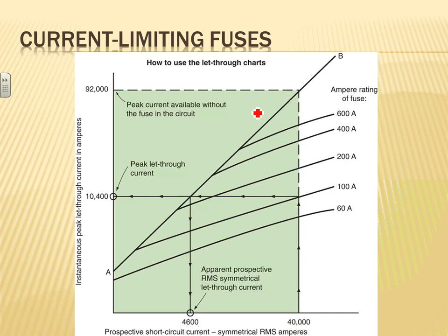So the more elevators you have, the easier it gets, because the individual overcurrent protecting device for each elevator is getting smaller relative to the main breaker you use to serve the feeder. But if you have 2 or 3 elevators, it can get really hard.